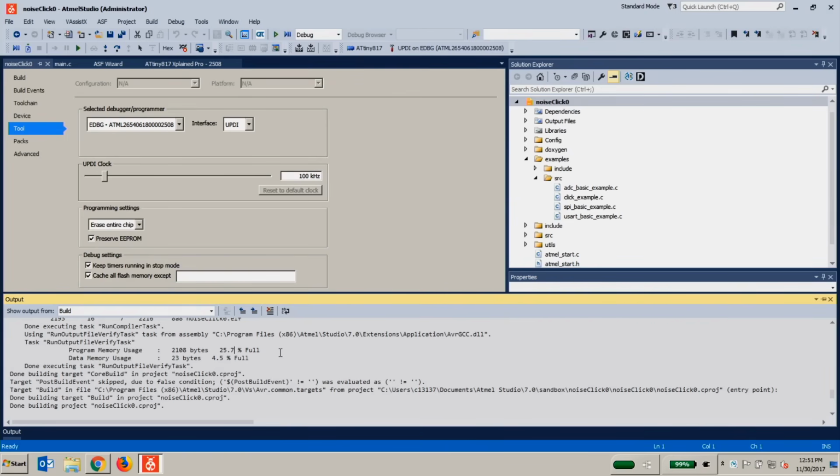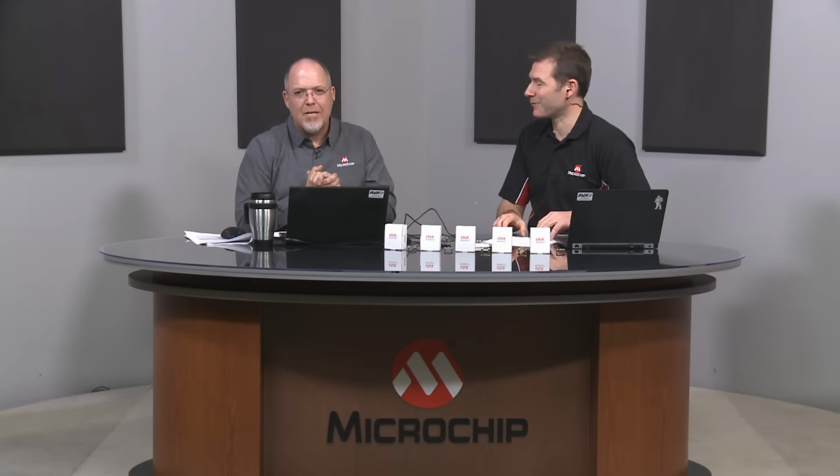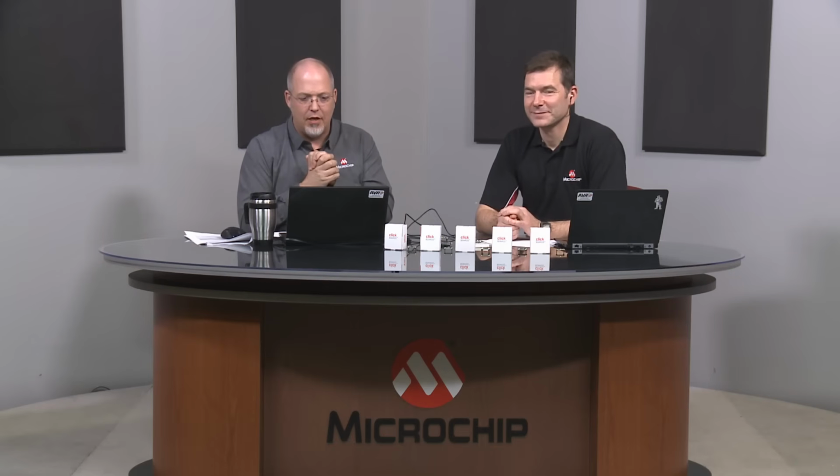Now, we're using it here today because we're communicating over the serial port. However, in a usual application, you may just be using this to trigger an LED or some other way of letting the user know that there's too much noise somewhere. Or send raw data through the UART. There you go. Then you're getting rid of the printf, and it gets rid of all that overhead from the STDIO library.